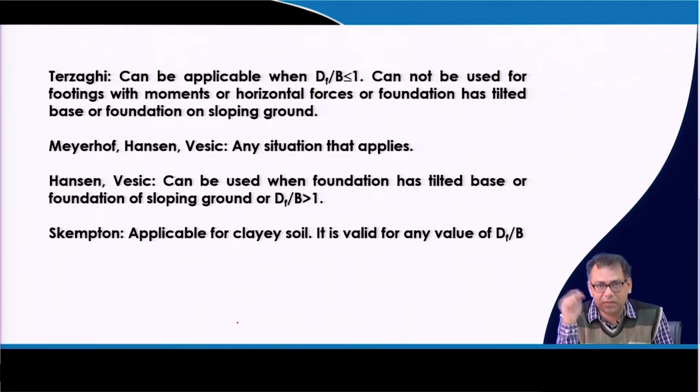If there is a movement, you cannot use. If there is a horizontal load, you cannot use that. If the foundation is tilted, you cannot. If the foundation is on sloping ground, you cannot. Even if the foundation is placed at a depth greater than the width B of the foundation, then also you cannot use the Terzaghi's bearing capacity equation.